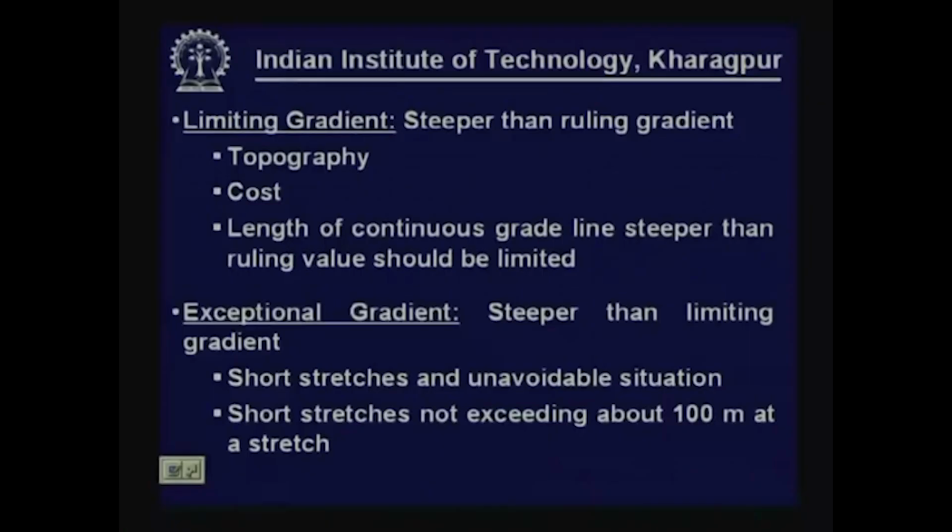But since exceptional gradients are much steeper, we should not use exceptional gradient for a continuous length of the stretch. It can be used only for a short stretch, normally not exceeding about 100 meter at a stretch. So, only for short length it is permissible.